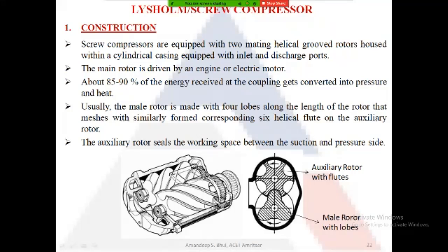The lobes of this bottom rotor, the male rotor, fit into the flutes of this auxiliary or female rotor. Okay, now on the left hand side you can see this arrangement, the cut section of this type of compressor, that is your screw compressor, is shown.